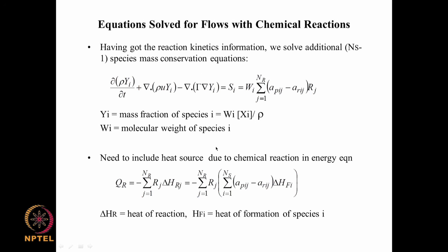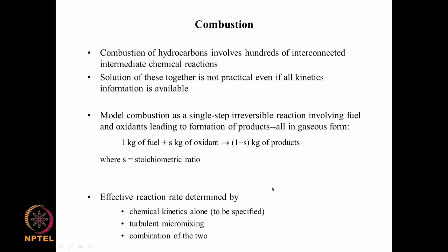The momentum conservation equations do not change except for the properties, which are now functions of the concentration of the species. And then the source term in the energy balance equation is given in terms of the rates of the reaction, the heat of the reaction and the stoichiometric coefficients. So this completes the formulation for a kinetics controlled reaction.